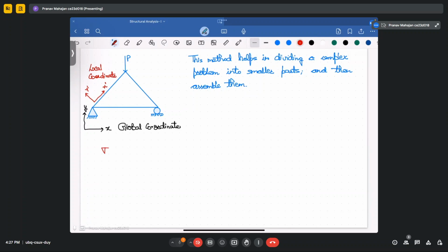let's start first with the stresses. Your stress will be E into strain, that is Young's modulus into strain. Now F upon A you can write as stress, but in this some more components will also be there due to the Poisson effect, and then E into U by L, where U is the deformation. Now how can you write this U?